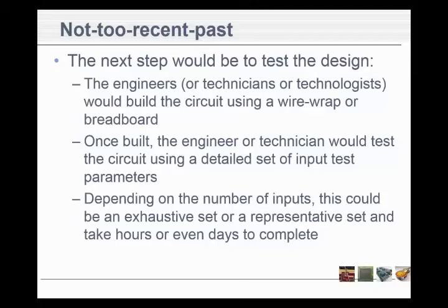The biggest thing that happened on that: you put on one side of the board, you put the chip in, and then you turn the board over, and that's where the pins were for the wire wrap. The biggest mistake people made was forgetting that you were flipping it over and the pin numbers changed. So a lot of them hooked those up backwards as far as the pin numbers were concerned.